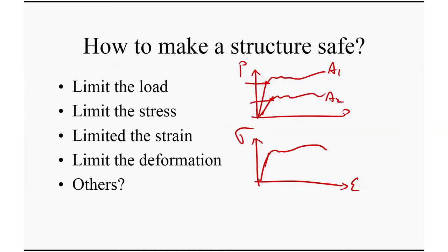Or I can say, just use the same material, so I just check each one's stress. Make sure their stress is not over here, then it will be safe, right? So as a general principle, which one is easier to say? The second one, because you just say stress has to be within this limit, the yield stress. So therefore, we oftentimes use stress to describe.